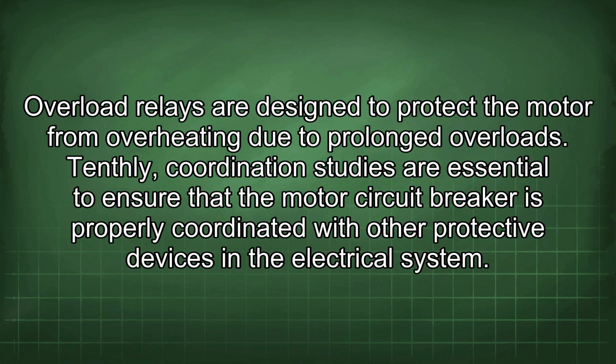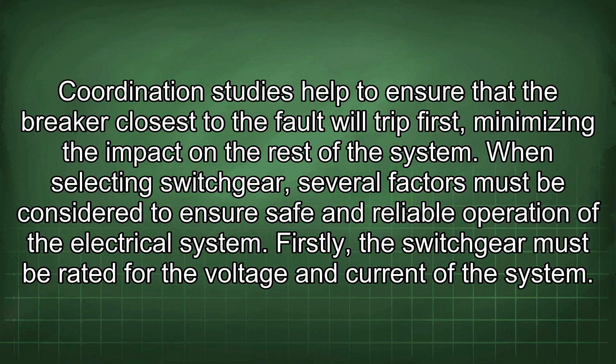Tenthly, coordination studies are essential to ensure that the motor circuit breaker is properly coordinated with other protective devices in the electrical system. Coordination studies help to ensure that the breaker closest to the fault will trip first, minimizing the impact on the rest of the system.